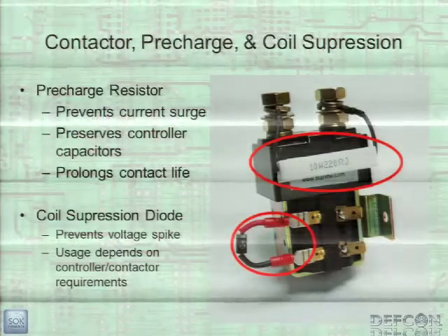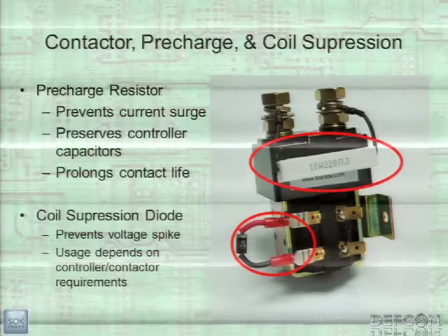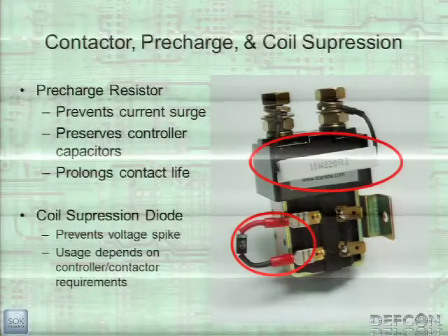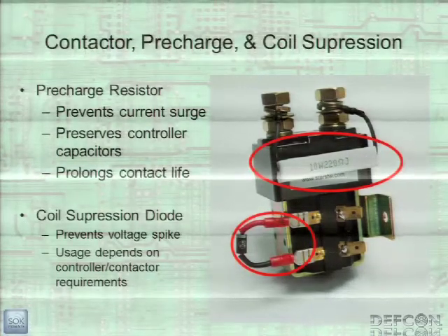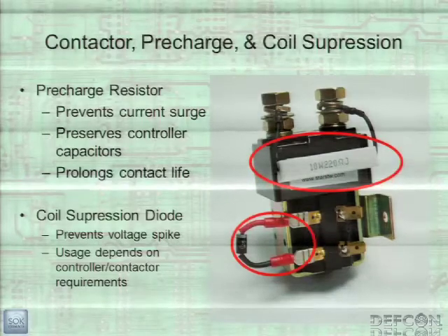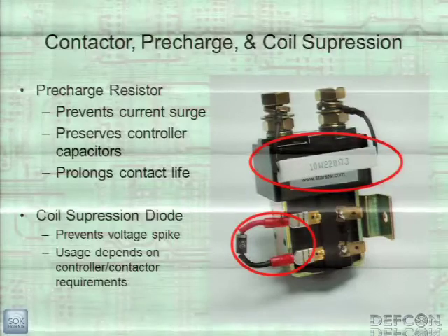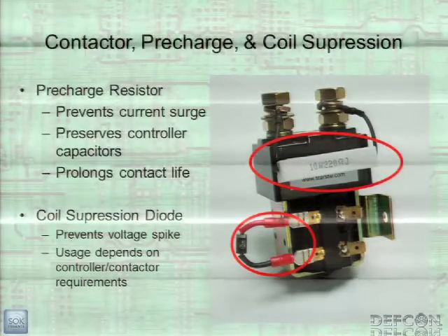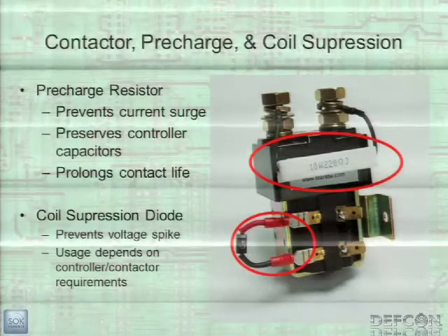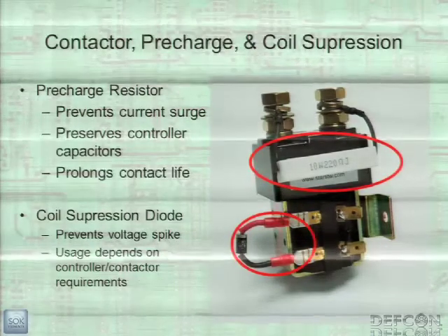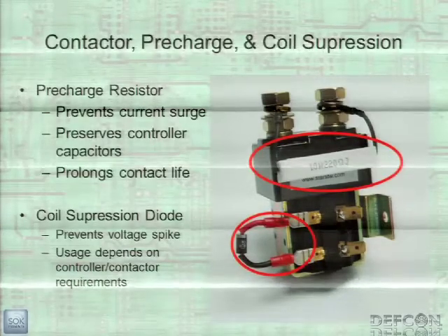An important thing to know about, and a common question that newbies have, is what's a pre-charge? Your contactor is a really big relay that's designed to handle the hundreds of volts that you're pushing through your electric vehicle. Your motor controller is full of large capacitors, and when they're empty and you turn on your relay and push the volts through it, your voltage differential is large, so the current goes to infinity. Obviously, infinity is a bad current to have in your motor controller.